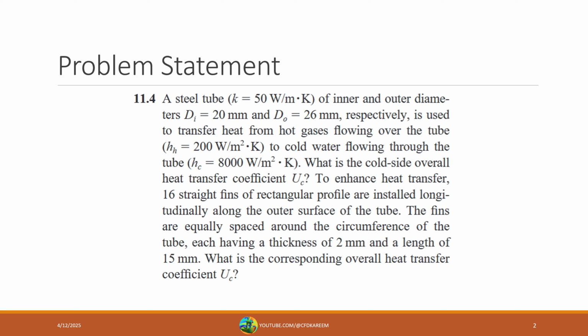The first question we're asked to answer is what is the cold side overall heat transfer coefficient U_C? And then the second part says, to enhance heat transfer, 16 straight fins of rectangular profile are installed longitudinally along the outer surface of the tube. The fins are equally spaced around the circumference of the tube, each having a thickness of 2 millimeters and a length of 15 millimeters. What is the corresponding overall heat transfer coefficient U_C?